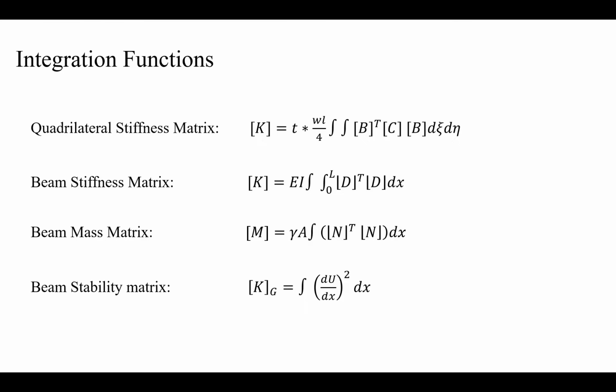If we have material nonlinearity, the C matrix would be nonlinear, and if we have geometric nonlinearity, the B matrix would be nonlinear. So the solution to this integral could be challenging. So we need to explore options for numerical approaches to find the integral.